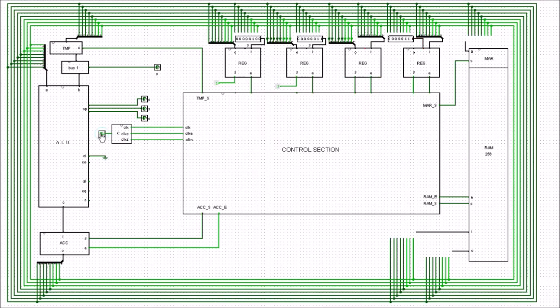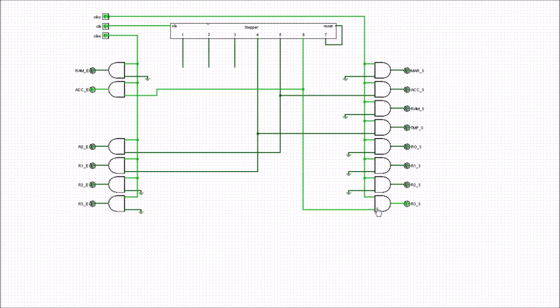So here's the next clock pulse here, and you can see that the value of the set has now gone high on register R3, and it's taken the information here from this bus and it's placed it into register R3, and there's the answer, 7 now sitting in that register. So that's us went through the whole process of adding 2 numbers together, and we've seen how it happens within this control unit. But of course, we're still to have a look inside here, which is the stepper or the counter, but I'll get onto that in the next video.